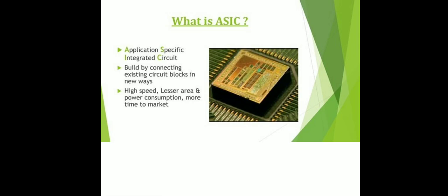So what is ASIC? ASIC is nothing but the application specific integrated circuit, which works by connecting existing circuit blocks in new ways. It has very high speed, less area, and low power consumption, but more time to market. As the name indicates, ASIC is a non-standard integrated circuit that is designed for a specific use or application.